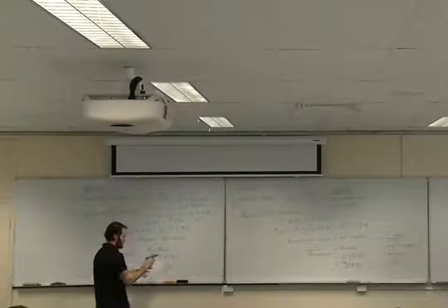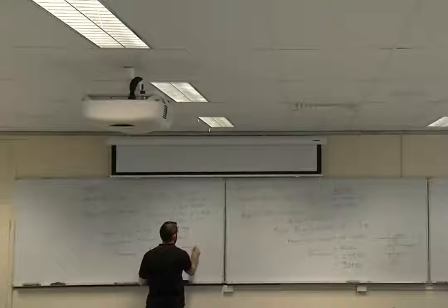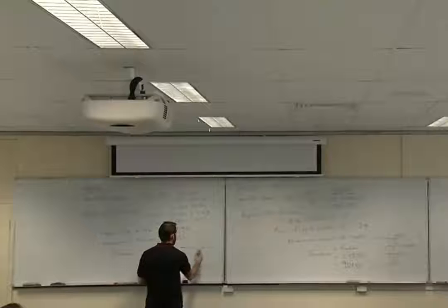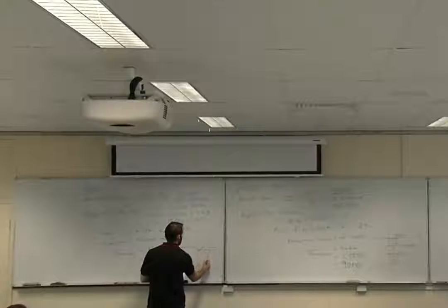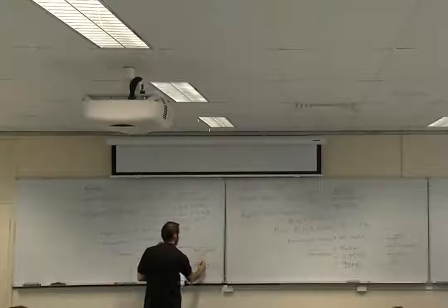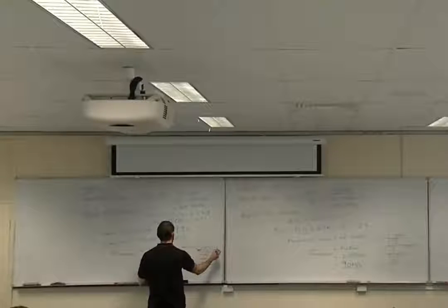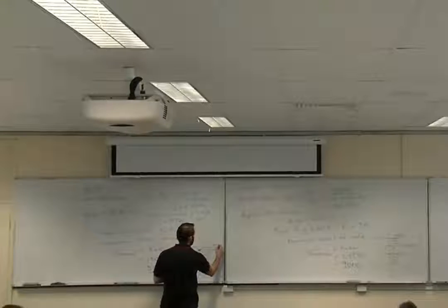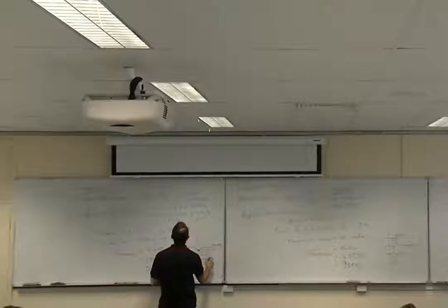So we'll underline that, and to stick with convention, I'll draw this so we're fully confident of what it looks like. We get this there and there being our critical zones. This value is 50.1 megapascals, and this value is 25.7 megapascals.